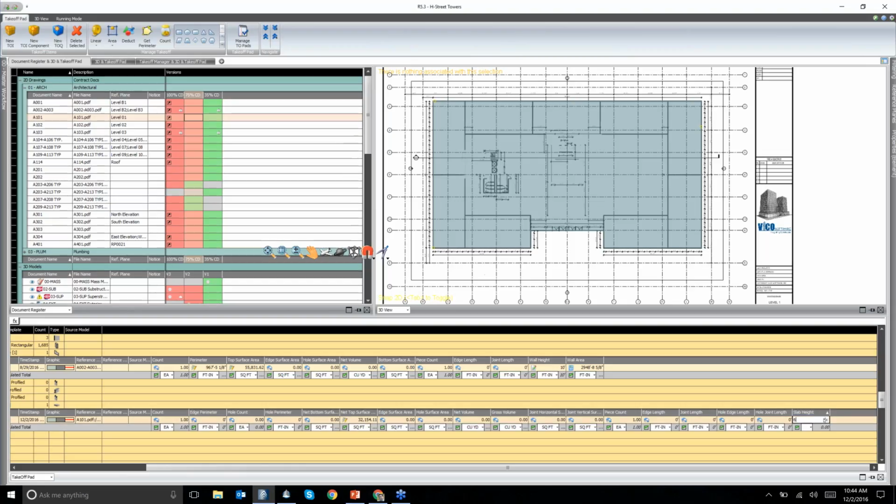And we're going to say it's 6 inches. So we'll pick our unit of measure. Here it is, square inches. I don't want square inches, I want inches. Feet, inches, there we go. I'll change that to 6.